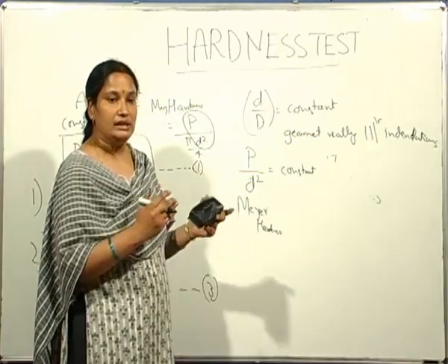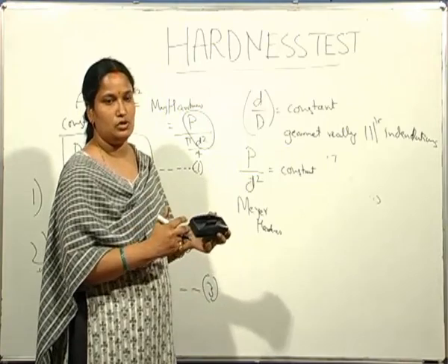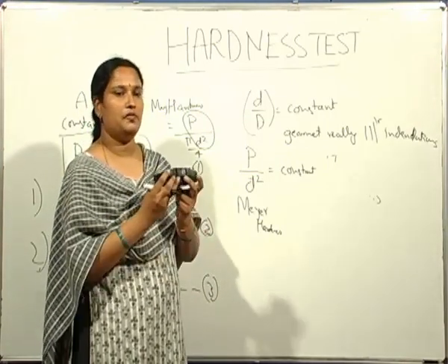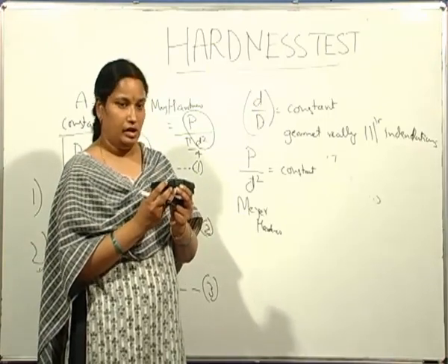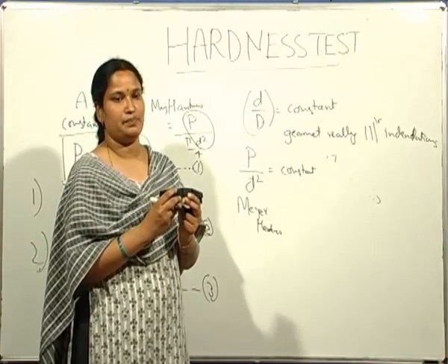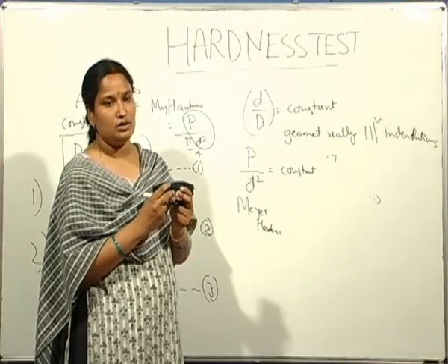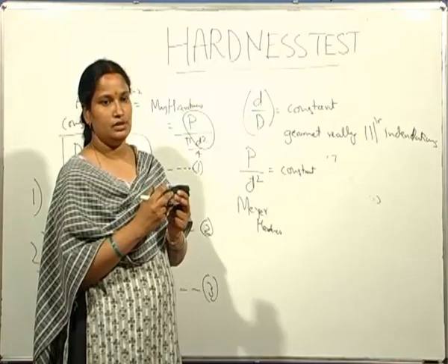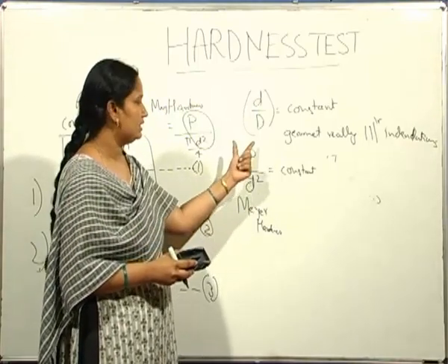It means that these hardness values do not vary with load for the same material. If for the same material one can produce geometrically similar indentations, then the hardness does not change with load. So this is given from this equation.